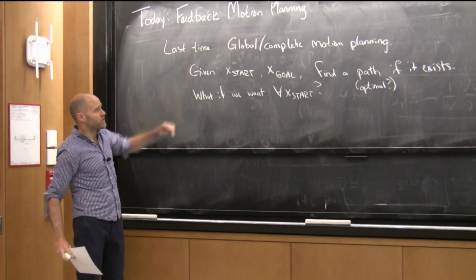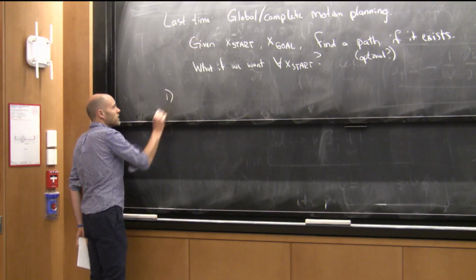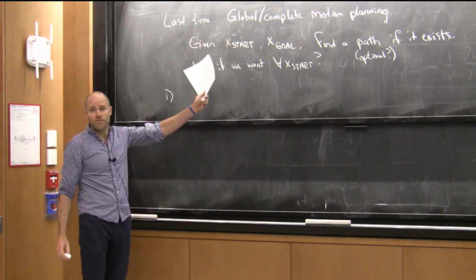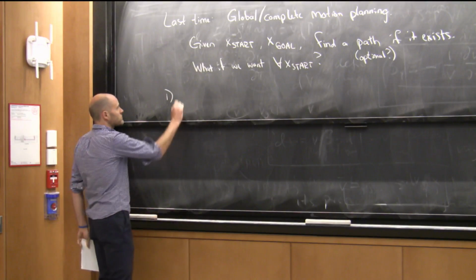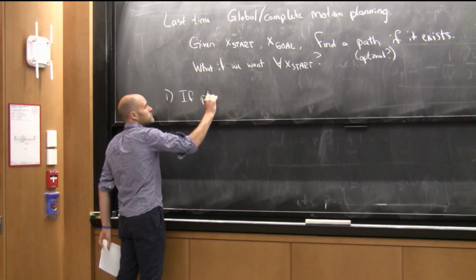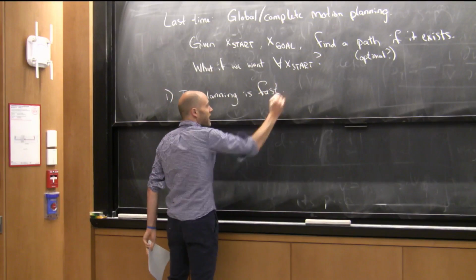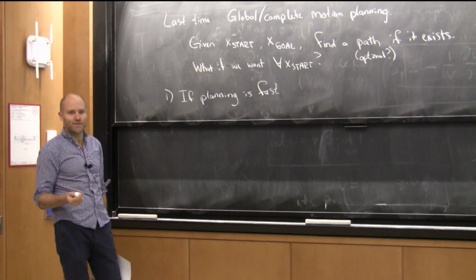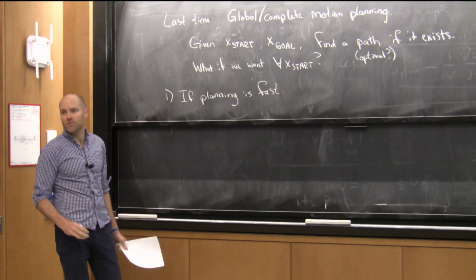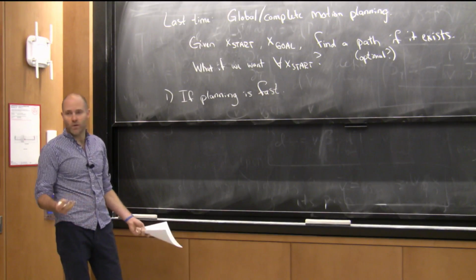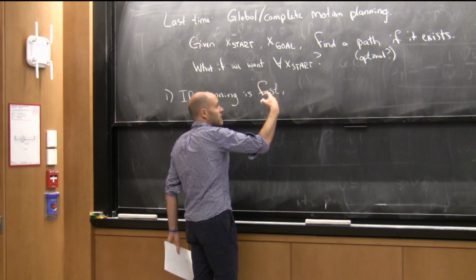So, given we have some of these tools already, there's a couple obvious things you can try to do, right? One approach would be, if you can plan fast enough, we talked about doing planning as a way to do feedback control, right? And fast, depending on the time constant of your dynamics in your robot, might have to be a kilohertz, and that's hard, but maybe you can get away with a lower update rate. If planning is fast, then the planner becomes a controller.